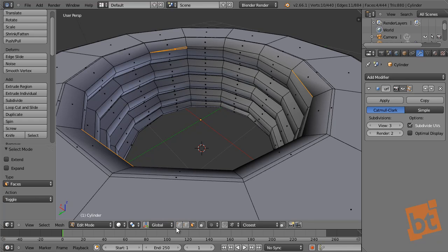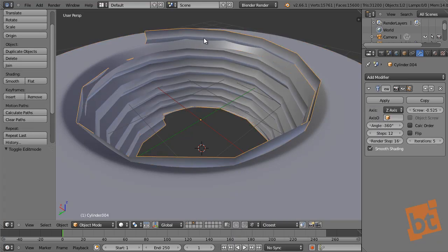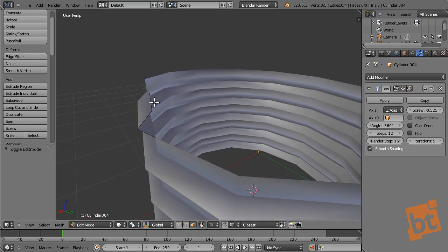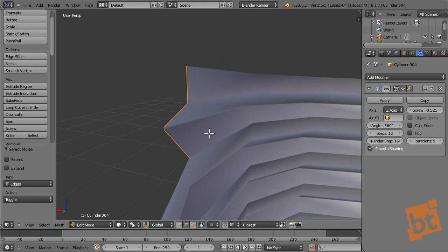So let's go to this layer, where we have the screw. Let me hide this. Okay, as you can see, the screw profile has 4 divisions: 1, 2, 3, and 4. That will generate 4 triangles. If we had 5 or 6, we would have 5 or 6 triangles. The reason I preferred an even number, 4 or 6, is that if we have 2 triangles close together, we can convert them into one quad, because 2 triangles make a quad. If we had one single triangle, that would be a problem, because we would need to add a lot of geometry to arrange it.